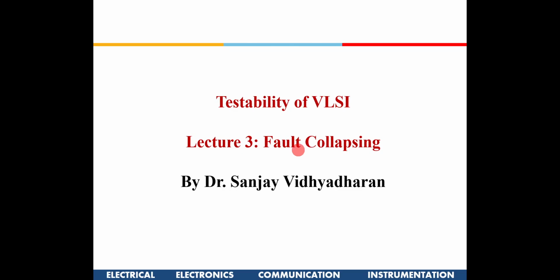So we learned that a better option would be to model all those defects as faults. There are certain kinds of faults like stuck at 0, stuck at 1. That means any net stuck at 0 is permanently at 0, or permanently at 1, irrespective of what is actually supposed to be there. And then we talked about delay faults, we talked about transistor faults, and there were 3 or 4 kinds of faults which we discussed, right?